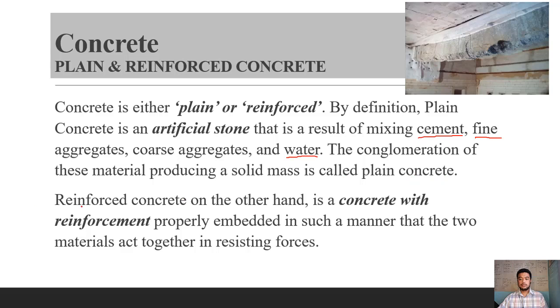Okay? Reinforced concrete, on the other hand, is a concrete with reinforcement properly embedded in such a manner that two materials act together in resisting forces, because concrete is very brittle. Therefore, as far as tension is concerned, it is really very, very weak.